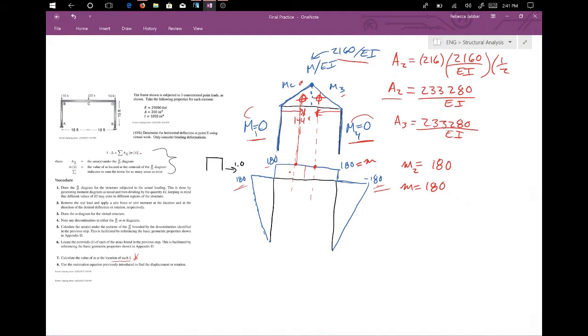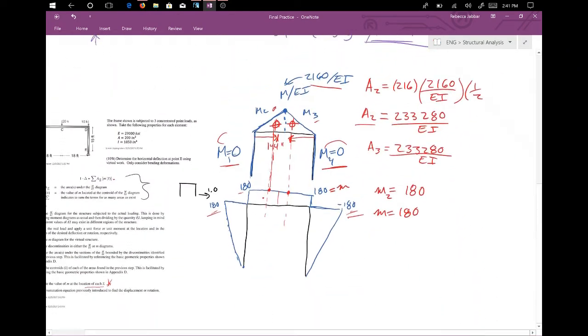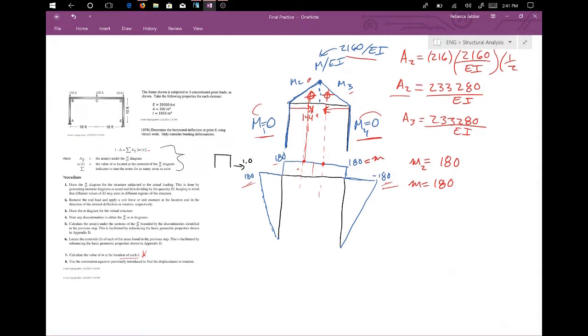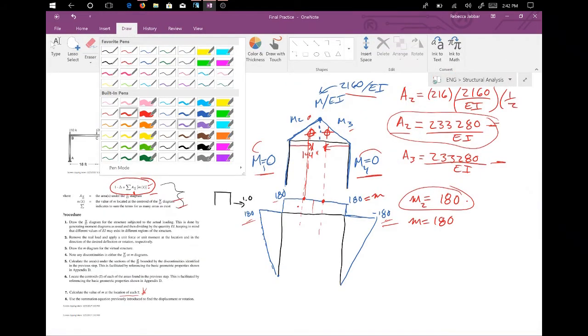It's that easy. And even if we didn't have this information right here, finding both of these moment equations, I hope, is pretty easy for you. So we're going to use this equation right here. Here's an explanation of what these mean. This is the area, this number that we got here, and this is that value of little m that we found with the location of the centroid, and all we're doing is multiplying these numbers with each other and then summing them up.